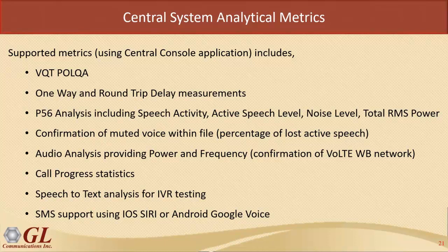From the vMobile, we'll be able to send and receive voice files at the same time, and then transfer the voice file to the central system, and that's where we'll do the analysis for one-way or round-trip delay measurements. We can also provide speech and noise level measurements, RMS power, and dropout detection, which is basically we'll record voice and analyze it against a reference voice file, and then let you know, yes, we had some dropouts in the beginning or the middle, some muted voice.